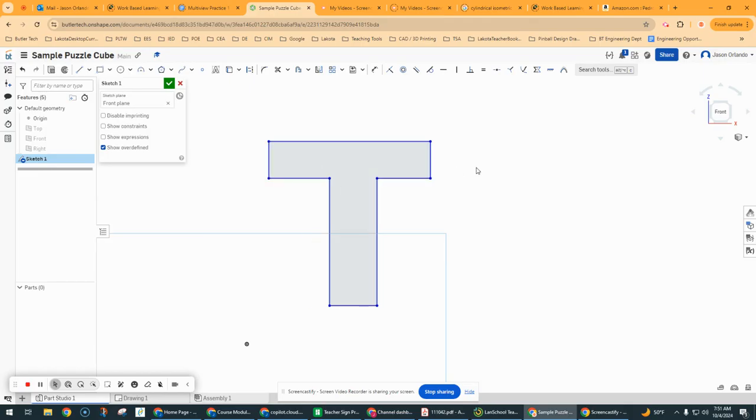All right. So by just making some lines, and as I was carefully making them, if I am intentionally clicking, getting those auto constraints of vertical, like you see on the screen right there, with that little vertical black line, here I'm getting a horizontal constraint, right? Then those lines have to be perpendicular. So as I click around, if I'm intentionally doing that, I may even get constraints as in 2 points that have to remain horizontal or vertical from one another. Okay, so this point right here has to stay aligned to that point.